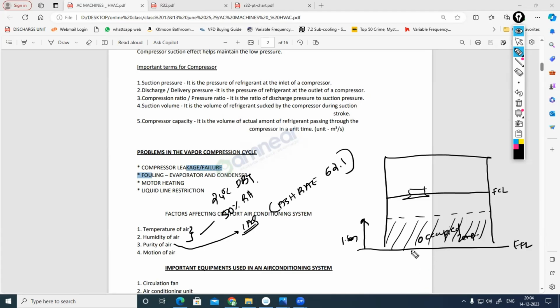As per ASHRAE, the optimum air velocity within the occupied zone, which we call terminal velocity, is 50 feet per minute. Feet per minute divided by 196.8 converts that into meters per second. So this 50 feet per minute is 0.25 meter per second. That's the optimum velocity.